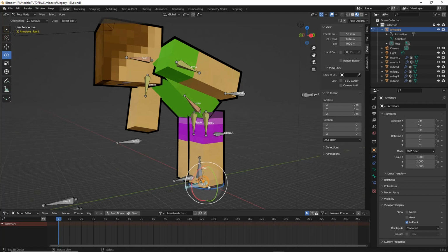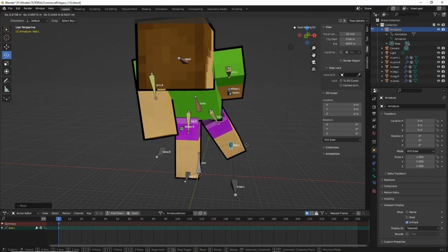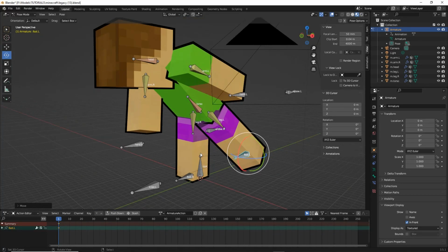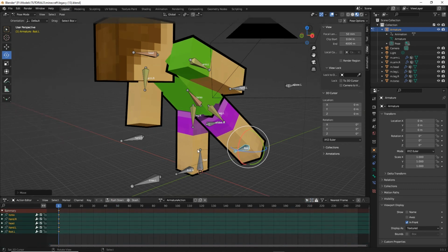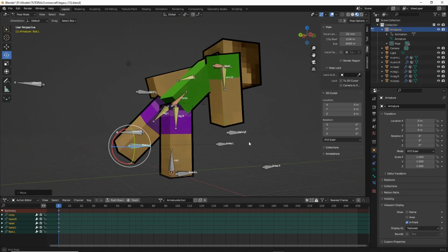Let's do the leg, so they're reaching down, and so we can see that we've got a marker for the bones that we've set, but we can only see the selected bone that we're editing. We want to see all the bones and the corresponding channels listed. So for that we want to disable this option, only show selected. So now we can see all the channels that we are adding a pose to.